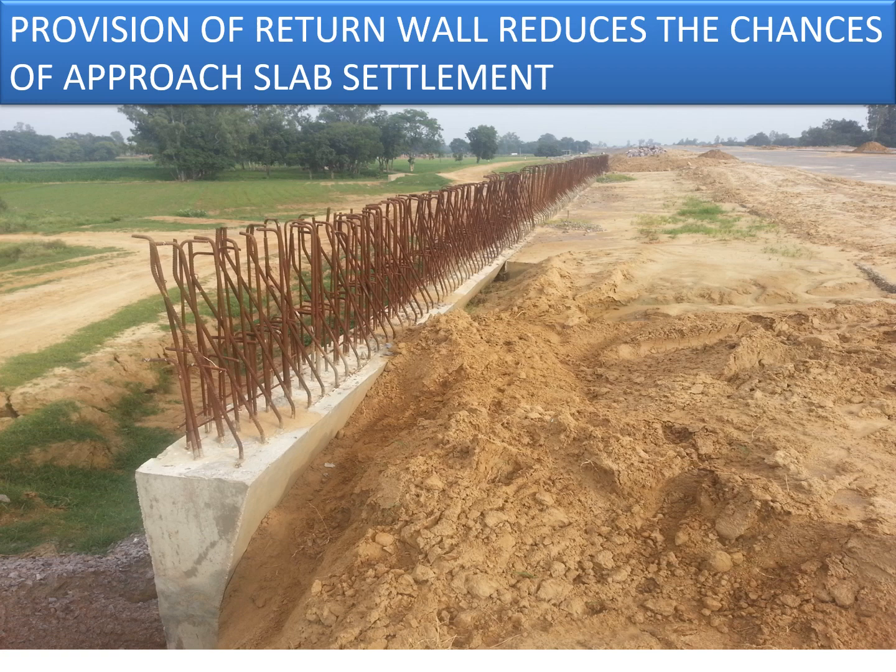But if you provide a return wall instead of a wing wall, as shown in the figure, then the area is confined with a return wall on both sides of the structure, and then the existing road which is coming from the other end. So whatever fill material is placed in that pocket, which is confined from all four sides, will not be prone to erosion or any soil movement. So the chances of settlement of the approach slab are minimal.